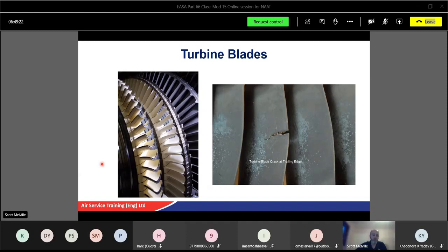So when you're viewing the aerofoil surface of the blades, the end of the probe located between the blades must be withdrawn prior to engine rotation. Be very careful, because you have to rotate the turbine using the gearbox to the HP spool, or an IP tool for the intermediate turbine. Nice and slow. Make sure you rotate first before you put the probe in. You'll be able through experience to know how far to put it in. If you put it too far in, you'll get the probe stuck in the tip here. I do have a photograph from the PowerPoint, and it's quite embarrassing. If you can't get it back out, unfortunately, that's an engine removal. So what was a serviceable engine, you've now made unserviceable. So please take your time. Again, you'll be fully trained on these.